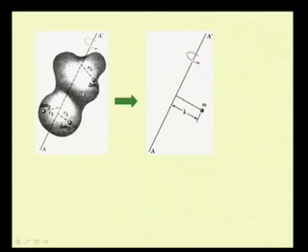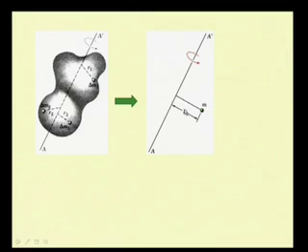So, now if we can find an equivalent mass, a concentrated mass m, which is equal to the mass of this entire rigid body, and if that is situated at a distance, say, a distance k, and the second moment of this element is the same as the second moment of the rigid body with respect to the given axis, say A prime, then we can call this distance k the radius of gyration.